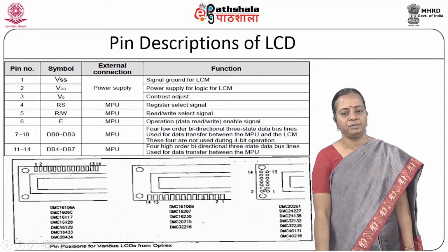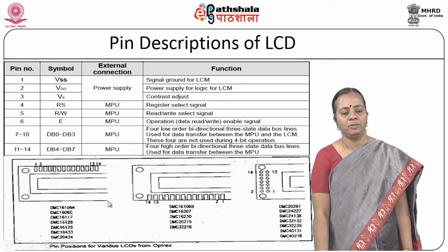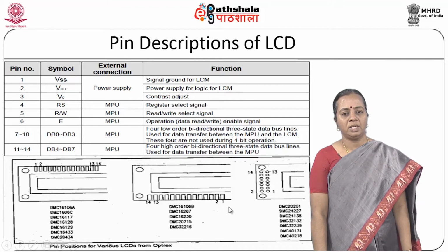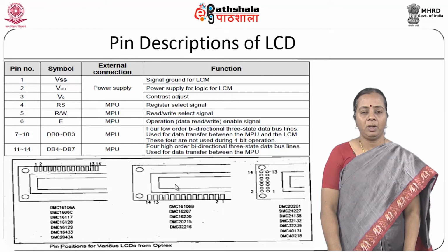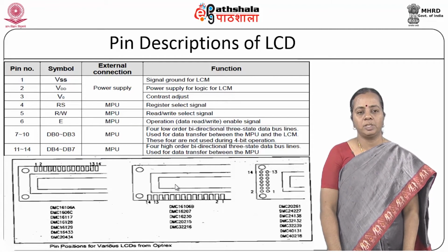So you see the different variety of pins available with your LCD. Here it is available as pins 1 to 14 on the top side. Here in another LCD, 1 to 14 is given on the down side. Sometimes the pins are also connected sidewise, 1 to 14. These are the pins that are very important when you are looking at your LCDs. While configuring, we have to look at these pins properly and connect them with your 8051 so that it gets interfaced.